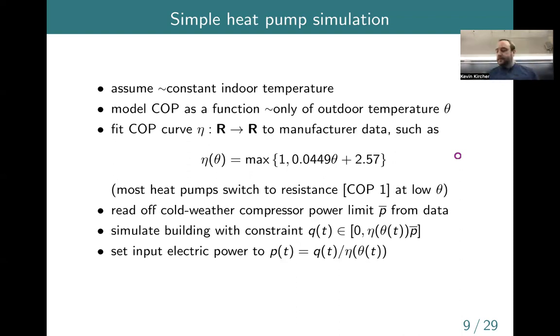So on the x-axis, basically you'd have the ratio of how hard you're working to the maximum power. You can think of it as basically the compressor speed on the x-axis. And then on the y-axis would be something like COP. You'd have different curves for different outdoor temperatures, but just assuming one fixed outdoor temperature, what does one curve look like? It's typically kind of a hill shape.